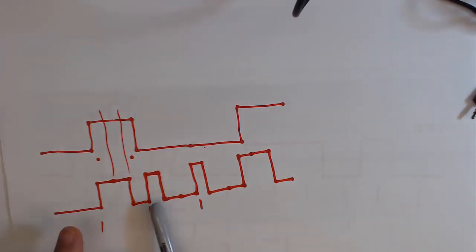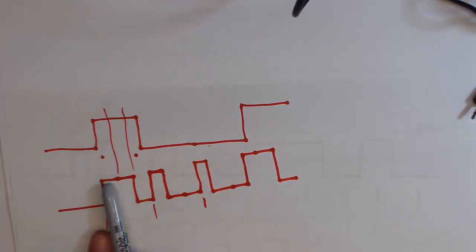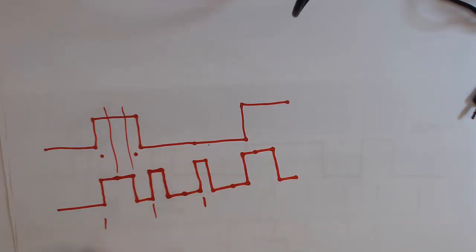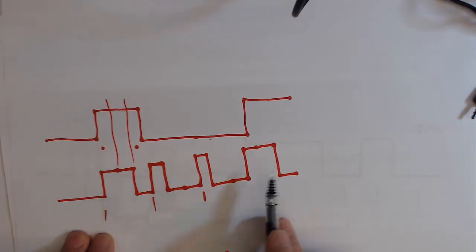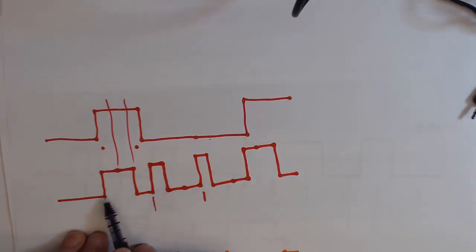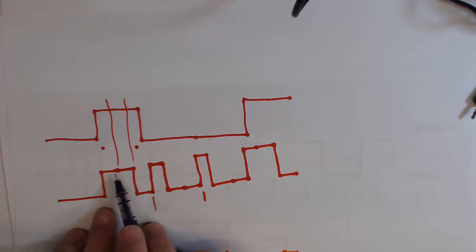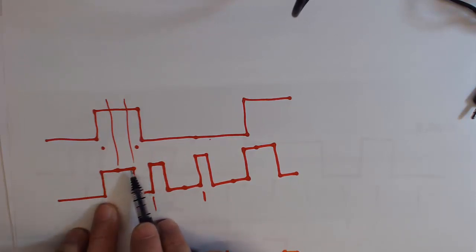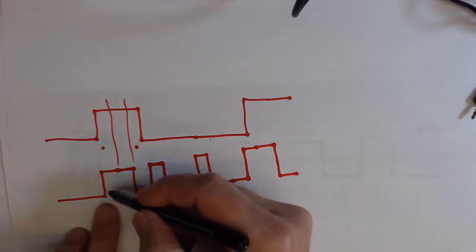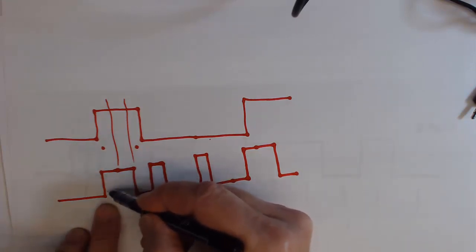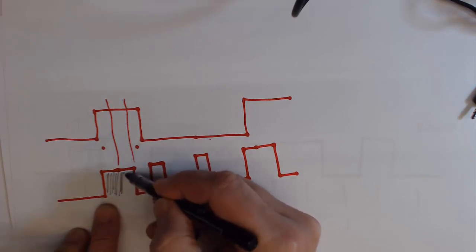So what we've done is we've taken each bit, divided it into thirds, and that third is always, first is the start bit, the last one is a stop bit, and the data bit is in between. Now of course we can't write DC to the tape. So rather than just have it go as a logic 0 and a logic 1, since we can only put AC on the tape, we have to create this as AC, and we call that a burst. So when this is logic 1, we're going to oscillate that.